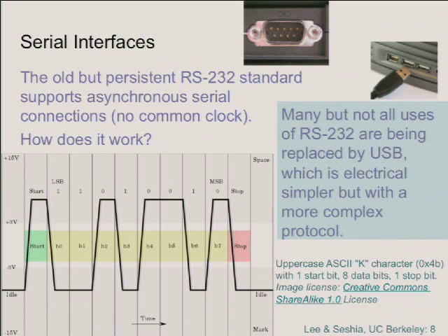At the receiving end, the circuitry is just sitting there listening, the line's idle, and all of a sudden the voltage goes high. It wakes up. It has to know what rate you're sending at, 58 kilobits per second, for example. So it sees the start line and says, oh, I better start paying attention, and it latches the voltages on the line at just the rate for 58 kilobits per second to get your 8 bits, and reads those into a register.